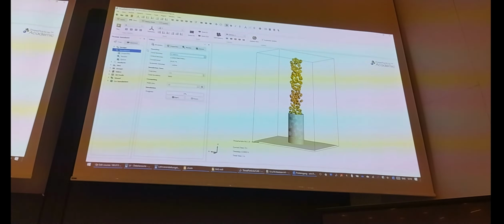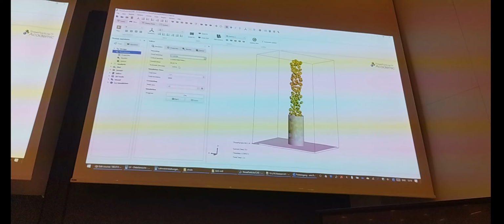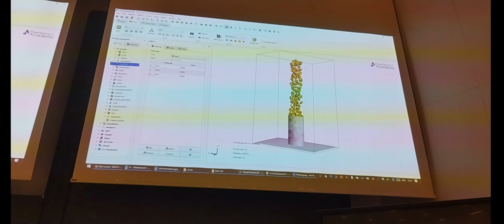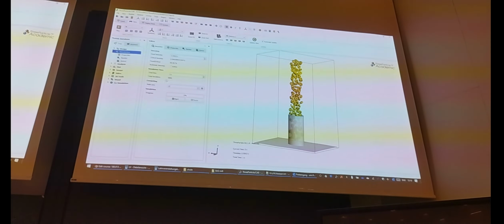Before I click on simulation, I want to show you what the shear modulus is all about. Why we set that with 5 instead of 10. Now remember, we have here around 30% of our critical time step. If I change the shear modulus of my bulk from 10 to 50, for example, it goes up to 66%. So decreasing the shear modulus gives me a much more efficient simulation.